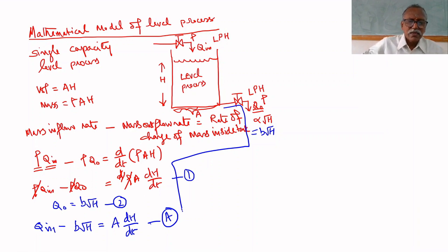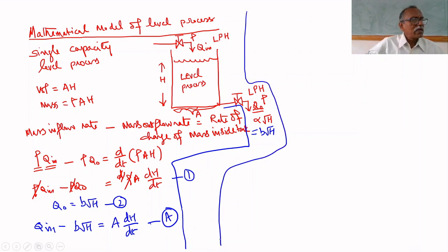Why? If you want a transfer function, the first step is we have to take the Laplace transform. But we cannot take the Laplace transform because of this nonlinear term. We can apply the Laplace transform only for linear relations. We can take the Laplace transform for a linear differential equation. For a nonlinear differential equation, we cannot apply it. Therefore, it's not possible to find the transfer function at this stage.